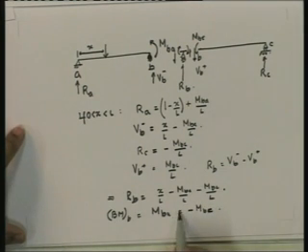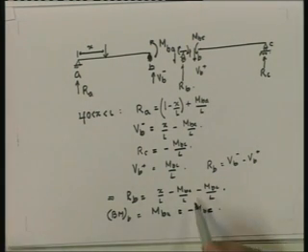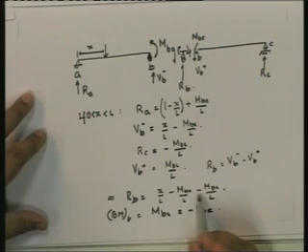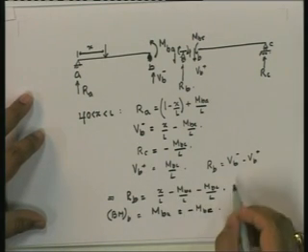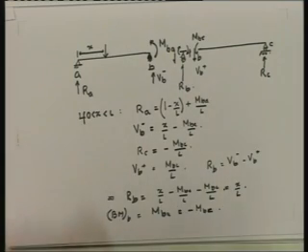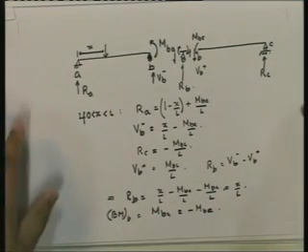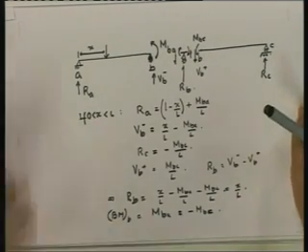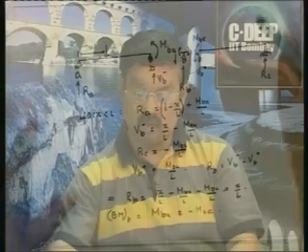In fact, MBA is equal to minus of MBC, and since MBA and MBC are minus, this actually ends up being x over L. Let us now proceed. This is if the load is between A and B. Now, these are the expressions. We found out everything.